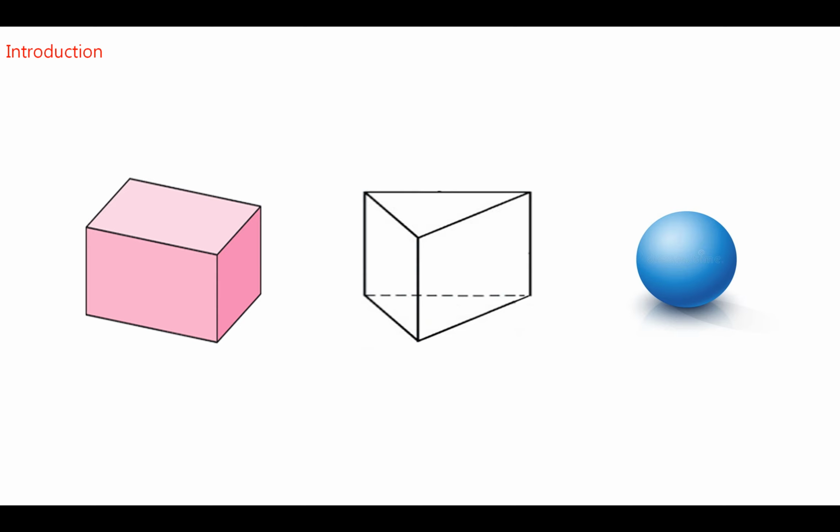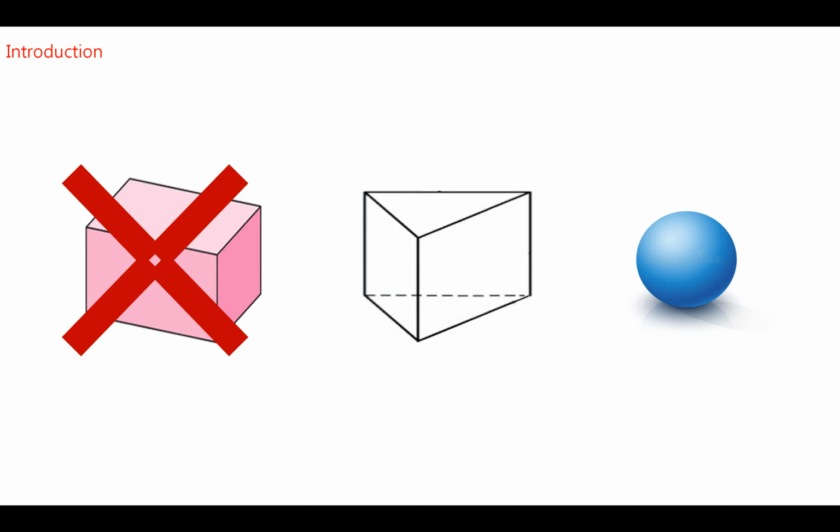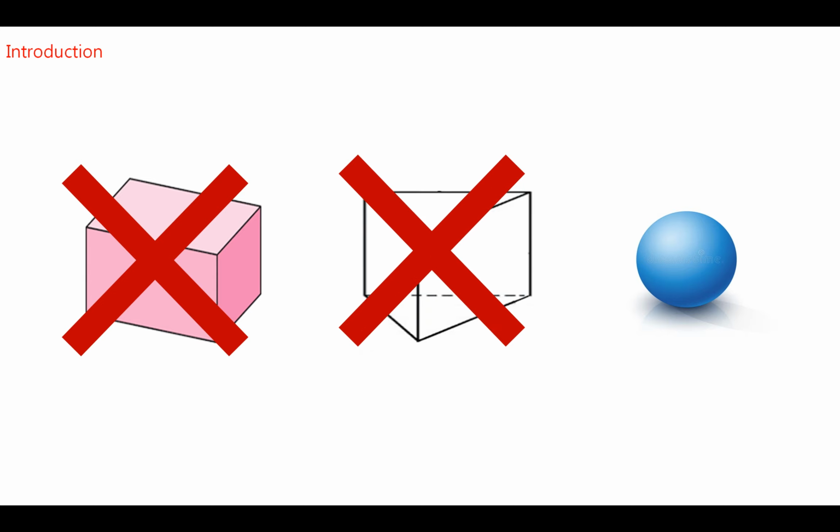First of all, it is very easy to notice that we cannot adopt angled geometry such as trigonal prism or cuboid. The reason is quite obvious, and that's because their angles introduce a large amount of friction to reactant flow, and thus resulting in larger pressure drop and lower conversion. It's quite obvious, right? So, there is no need for us to use such reactors even if it is possible.